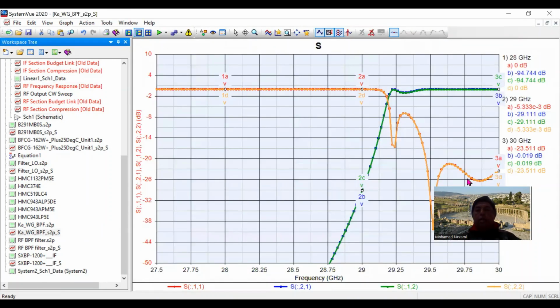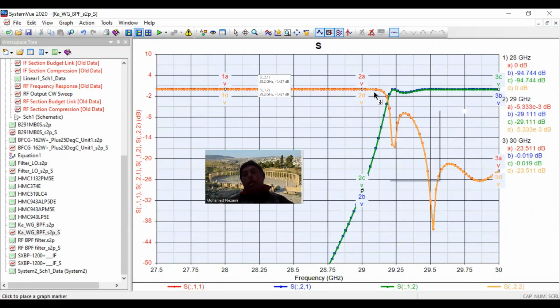Okay, so this is what you can see in here when you look at this. This is basically all it is, a waveguide, really. The dimensions of the waveguide were designed so that the TE10 mode has a cutoff frequency at around 28 gigahertz or so. Okay, well, around 29 gigahertz. So the LO is 28, as you can see here. The LO is down at 29 gigahertz.